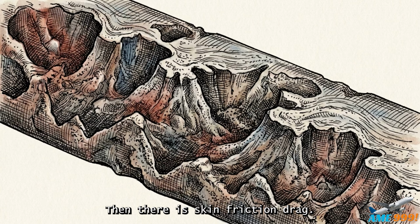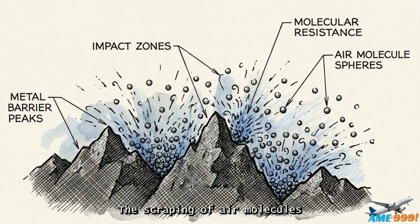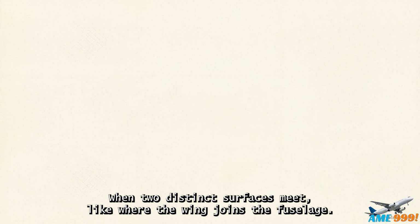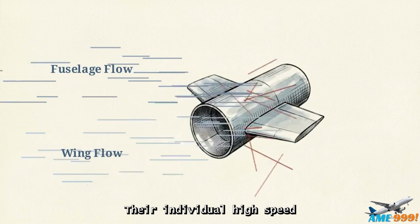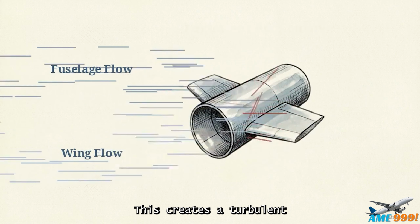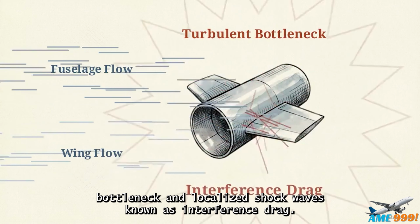Then there is skin friction drag. This is the direct result of the viscous boundary layer, the scraping of air molecules against the microscopic roughness of the aircraft's surface. When two distinct surfaces meet, like where the wing joins the fuselage, their individual high-speed airflows are forced to mix in a restricted physical space. This creates a turbulent bottleneck and localized shockwaves known as interference drag.